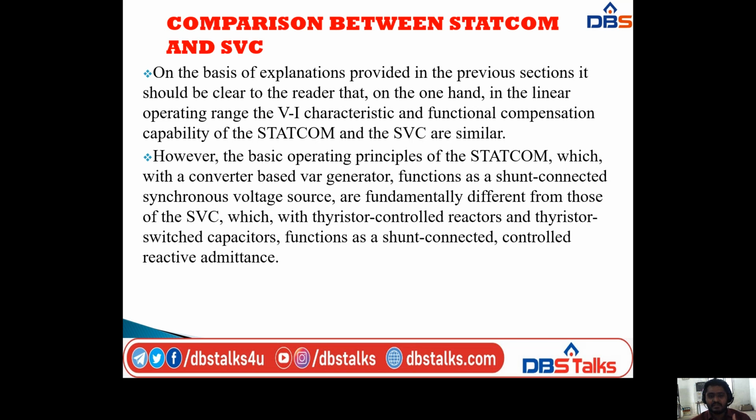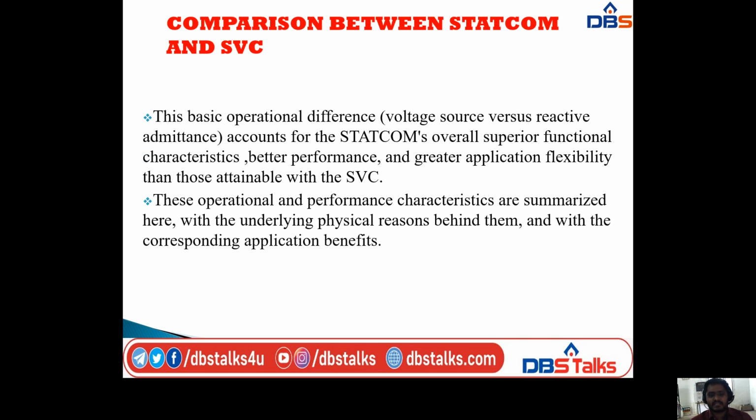In the SVC we are using thyristor-controlled reactors and thyristor-switched capacitors, that is the TCR and TSC, and it functions as a shunt-connected controlled reactive admittance, but the STATCOM functions as a shunt-connected synchronous voltage source. The basic operational difference, voltage source versus reactive impedance, accounts for the STATCOM's overall superior functional characteristics, that is better performance and greater application flexibility than those attainable with the SVC.